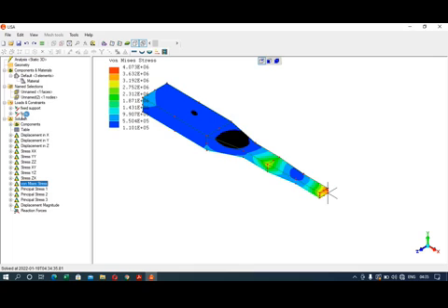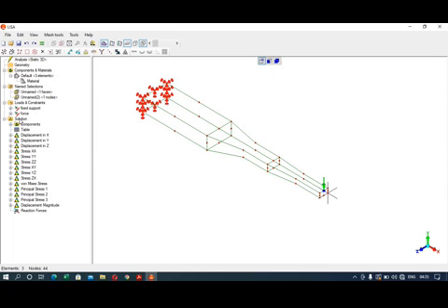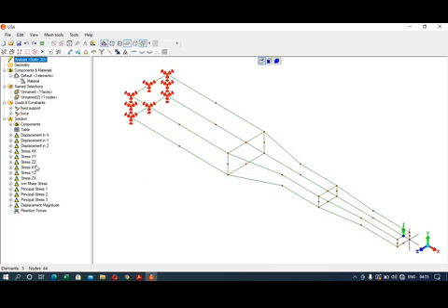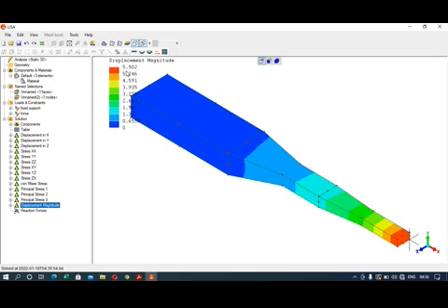So now I will double click on this force and I will double this force from 1000 to 2000. So click on OK. Again right click this solution, solve. Now check the von Mises stresses. The value is 8.14 into 10 raised to the power 6, and the displacement magnitude is 5.902.